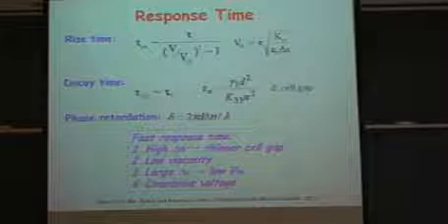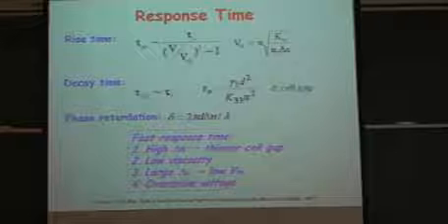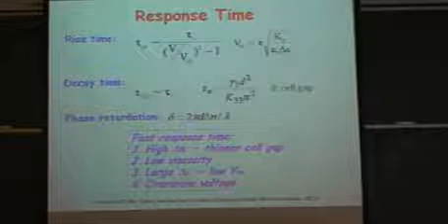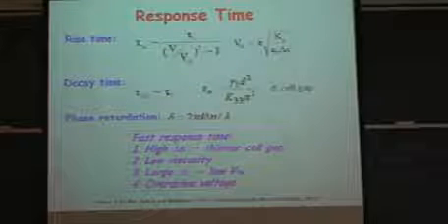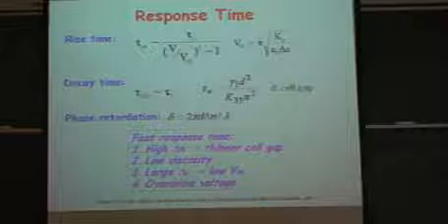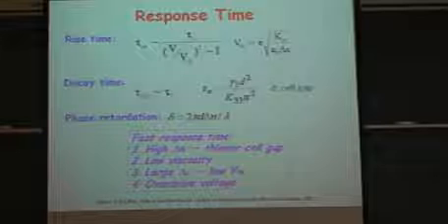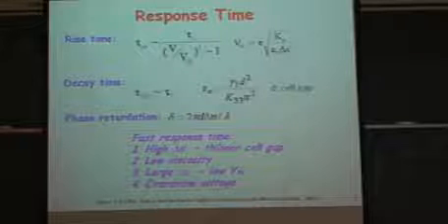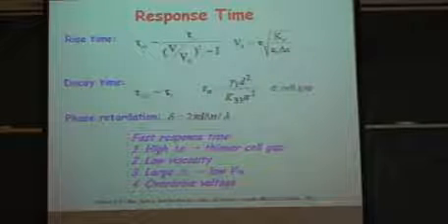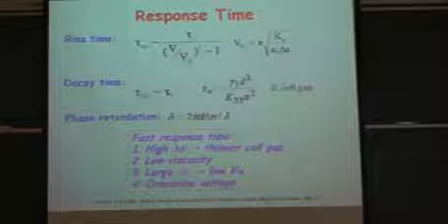So this equation is about the rise time and decay time. For example, in liquid crystal applications, we usually use a liquid crystal cell with a parallel glass structure. On the glass substrate we spin coat an ITO electrode, and on the ITO electrode we spin coat a polyimide layer. Then we use cloth to buff the polyimide layer and induce the rubbing direction and pre-tilt angle. So we fill the liquid crystal into the cell.